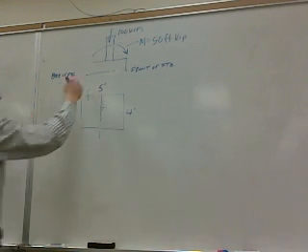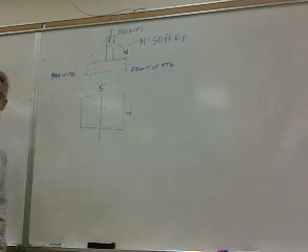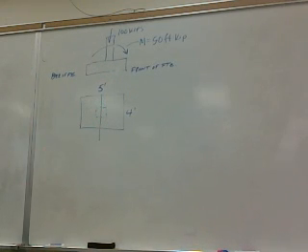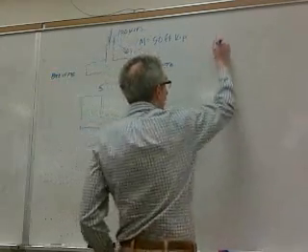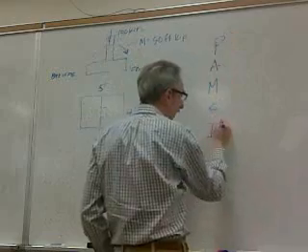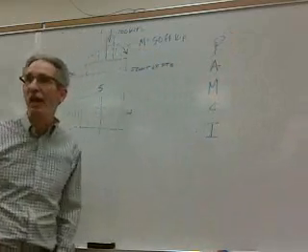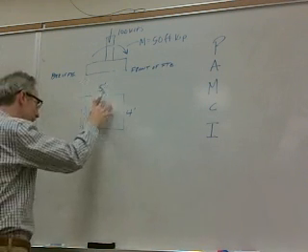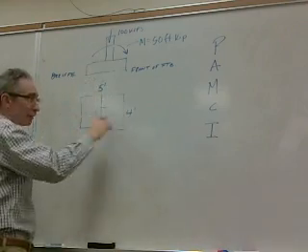Okay? So there's a couple things I like to do. Once you've said, yeah, hey, I've got a combined stress situation, I think it's simpler for everybody if you just go ahead and list out the different things that you need to know. So, P over A, so I need P, I need A. MC over I, so I need M, C, and I. This is sort of a plan view of the footing.